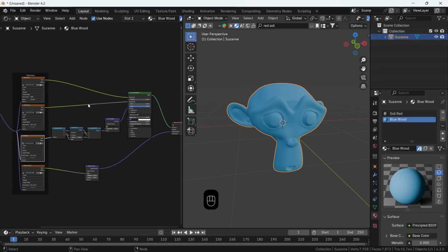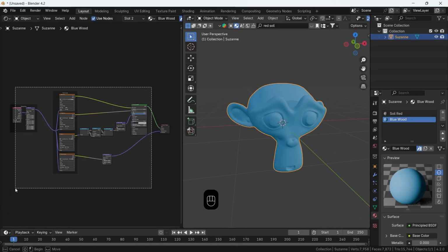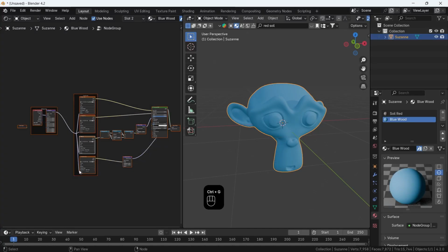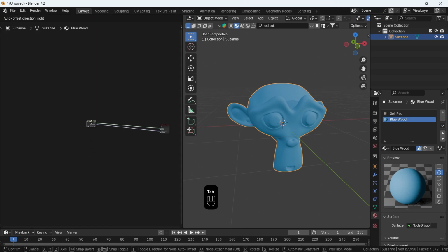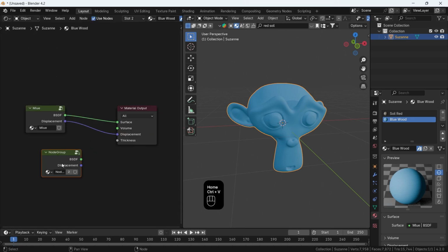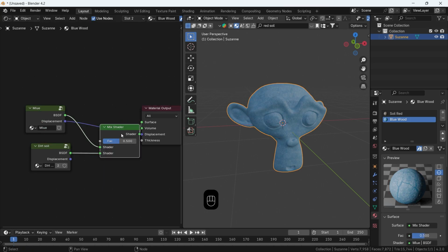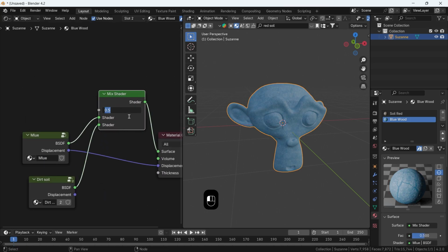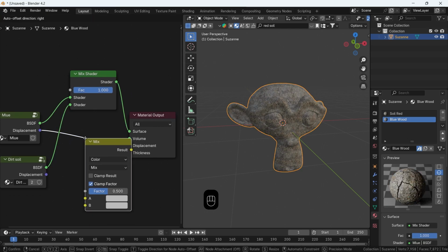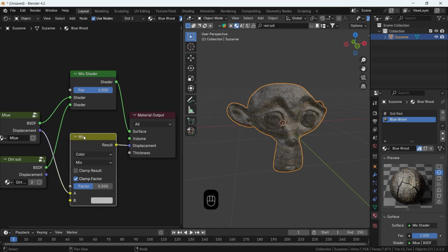If you have a mesh like this monkey head with two materials, the normal way to mix those two is by making them into group nodes with Ctrl-G, copy one into the other, and mix them with the mix shader. The 0 on the mix factor will be max top slot, the blue, while the 1 value is max bottom slot. The displacement can also be joined with a color mix with the same arrangement, and now the basic